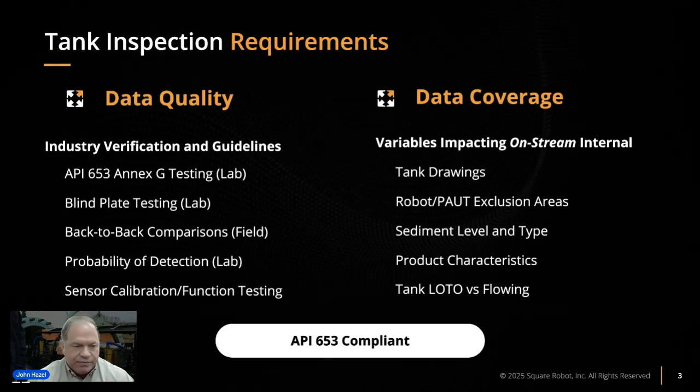And I know that's going into a different document, but we've also done a number of things across our timeline here. We've had blind testing. We've done back-to-back field comparisons where the tanks that we've inspected have been followed up with MFL inspections a number of different times to compare results. We've also done a lot of lab work on the probability of detection, looking at a number of different defects, and also making sure that we can prove that our sensors are calibrated and they're functioning correctly.